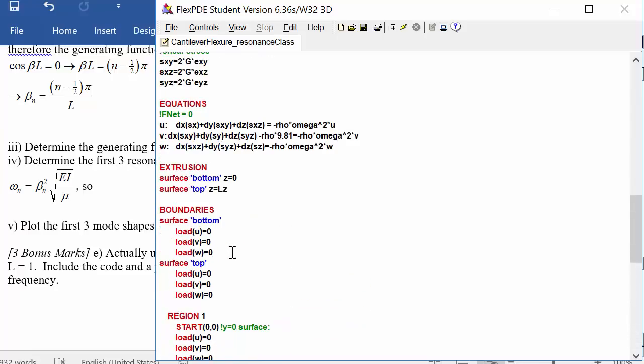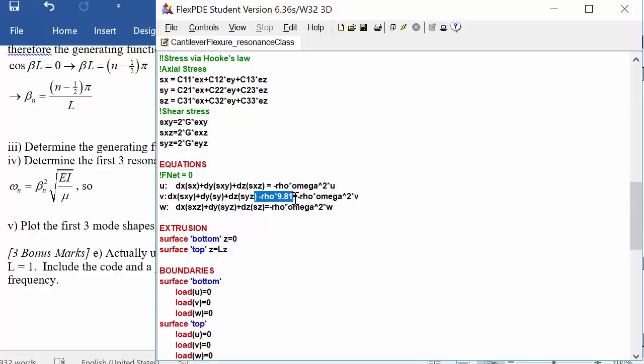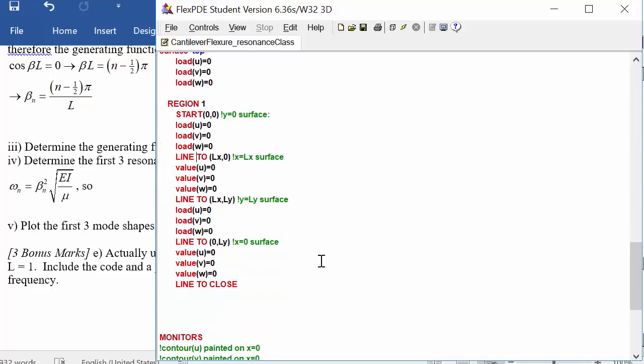We're also going to need to set up the boundary conditions. And maybe to start things off, since the density is so huge, let's pretend we're not on Earth. We'll go 9.81 over 1e5 just to make it a much smaller perturbation in y so that doesn't mess things up. Okay, so at the x equals Lx surface, we need that it is free in y, but it can't actually angle, so that's fixed in x.